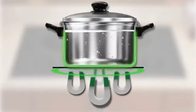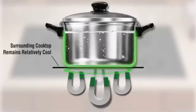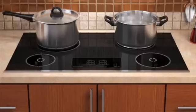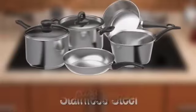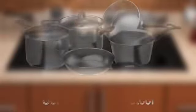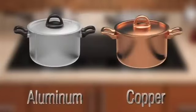As such, less heat is lost from inefficient thermal conduction between the heating element and the cookware, making the surface safe to touch. Induction cooktops are only able to couple with ferromagnetic cookware due to their high magnetic permeability and resistivity, such as cast iron and some alloys of stainless steel. Thus, modern induction cooking technology is not compatible with cookware made from glass, ceramic, aluminum, or copper.